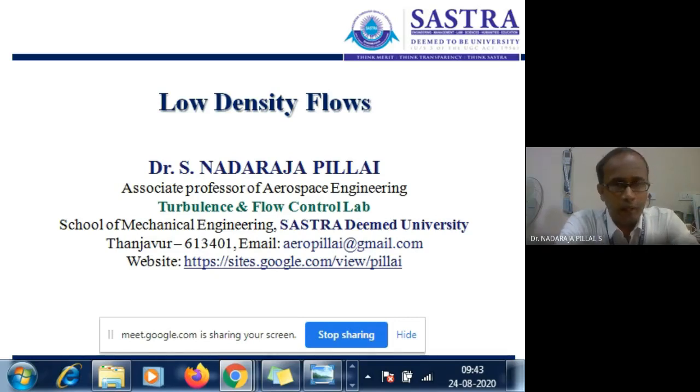So far we had a discussion on hypersonic flow, and now we have moved from saying hypersonic flow by the rule of thumb that the Mach number is more than 5 or 6, to the point where we can say that if phenomena such as thin shock layer, entropy layer, viscous interaction, and high temperature flows are present, where the temperature is high enough to dissociate the air into ions, then we can call that particular flow hypersonic flow.